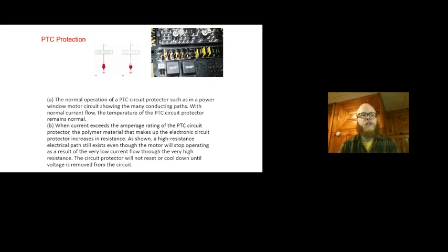Alright, so this PTC protection is very similar to a circuit breaker in the fact that we just have to wait for it to cool back off and the resistance will come back down for us. It's built into some computer circuits, definitely not all, but some computer circuits, and is there to protect things. You'll see it on lighting circuits as well, because sometimes when a light bulb burns out, the filament will drop down into the bulb and can sometimes create a short circuit that way, or because it fails by melting, so when it melts it could just create a short circuit.